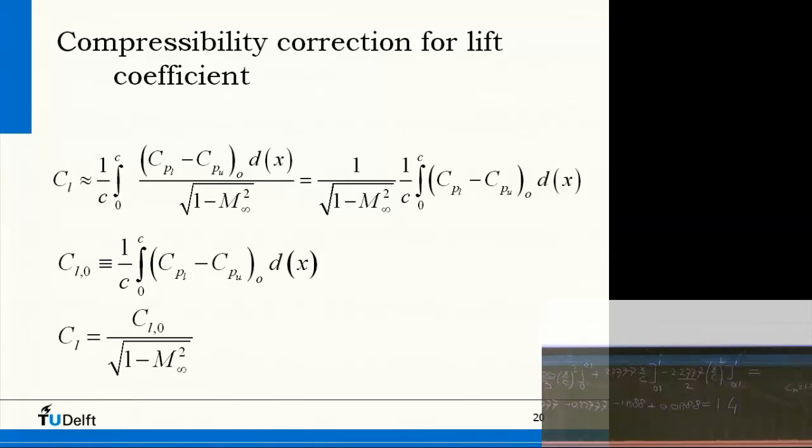Well, if we would have wanted the lift, if it was at small angles of attack, we could also say, okay, then the lift coefficient is the same as well, right? Now this is all with CPs, sort of the incompressible CPs. If we're interested in the higher Mach numbers, we need the same compressibility correction as we did for CPs. So again, the Prandtl-Glauert rule. So the CP, the incompressible pressure coefficient, dividing by the square root of 1 minus Mach infinity squared. And please note this is at infinity. This is at free stream again.